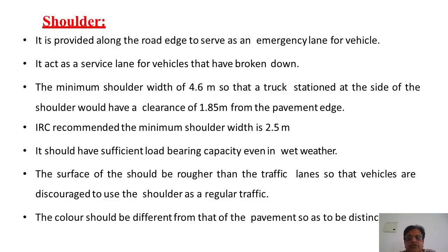It should have a sufficient load bearing capacity even in the wet weather. It should have sufficient strength because the trucks usually will be loaded. Due to that loading, sometimes if the shoulders are not properly built or if the shoulder is not having a sufficient capacity, it may sink, it may go down. That should not happen. So for that purpose, it should have a sufficient bearing capacity.